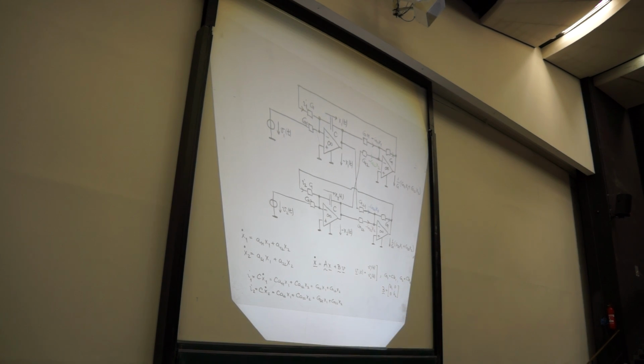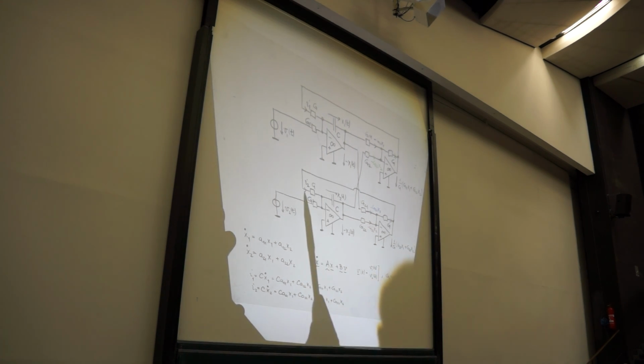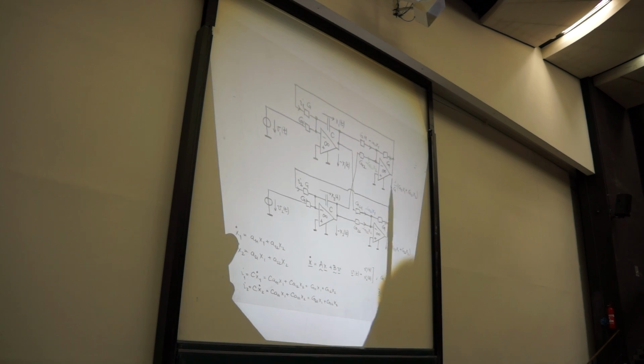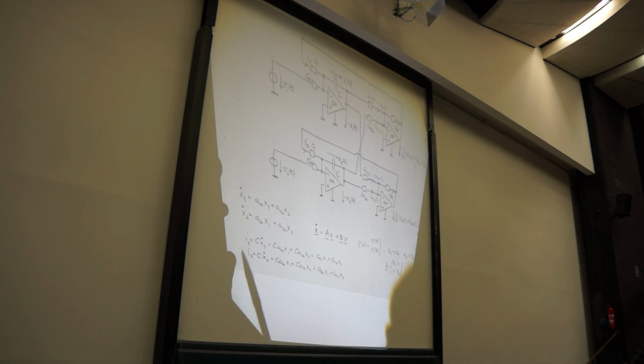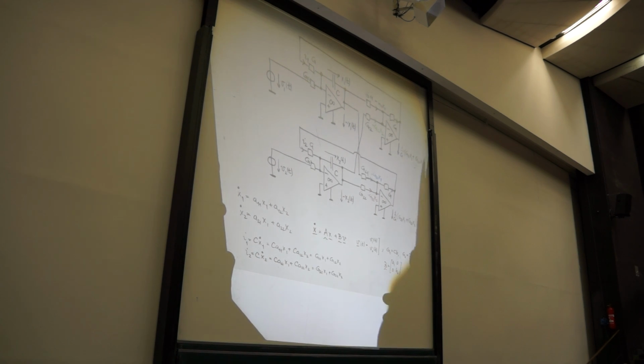It will be the same current because it's the same potential there. This current, I1 and I2 respectively, simply will be that voltage multiplied by this conductance, and that gives us these currents here. These parenthesized expressions are actually current I1 and current I2.